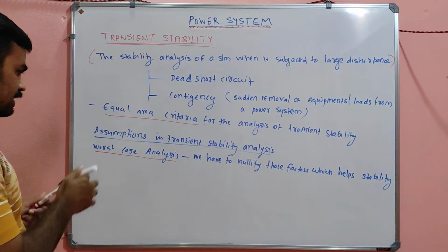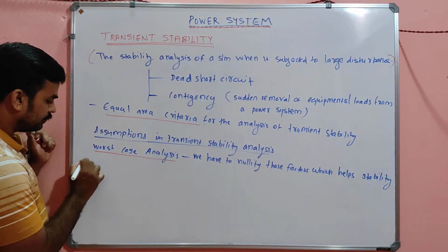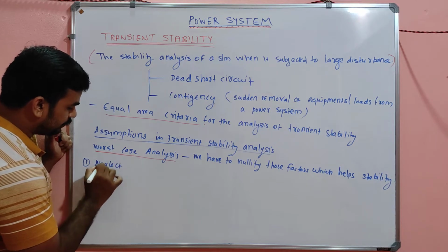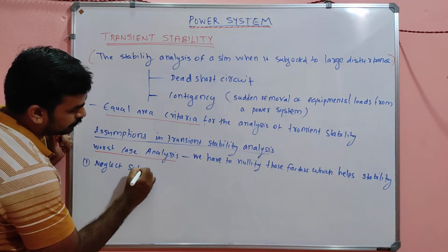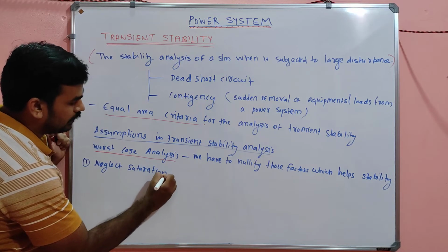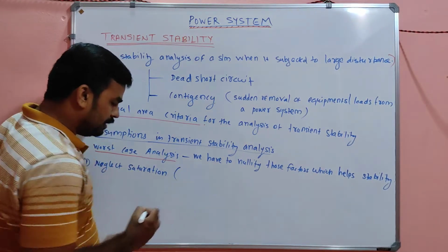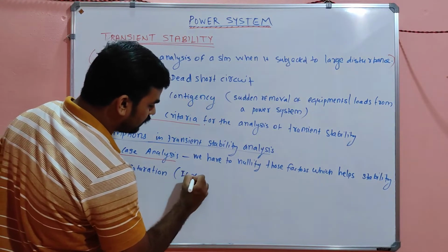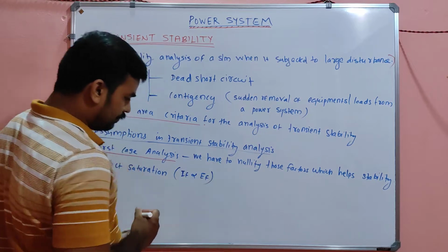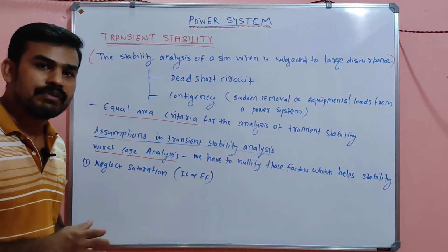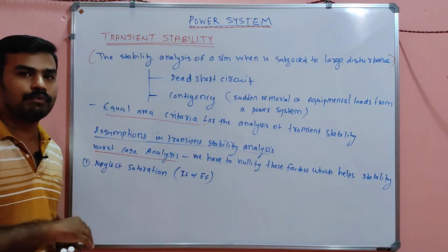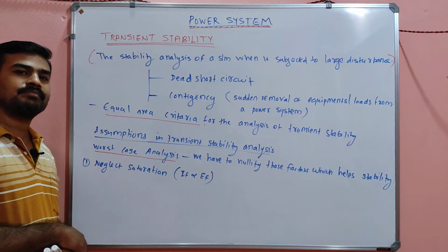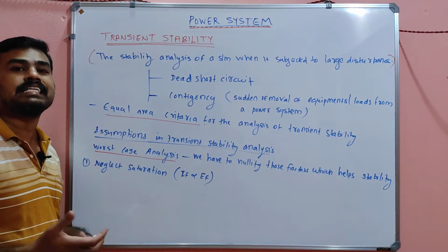So the first assumption is to neglect saturation. What does saturation mean, my dear? There is a relationship that the field current is directly proportional to EF. Whenever we increase the field current in the rotor of a salient pole or cylindrical alternator, any alternator, the induced EMF EF also increases.